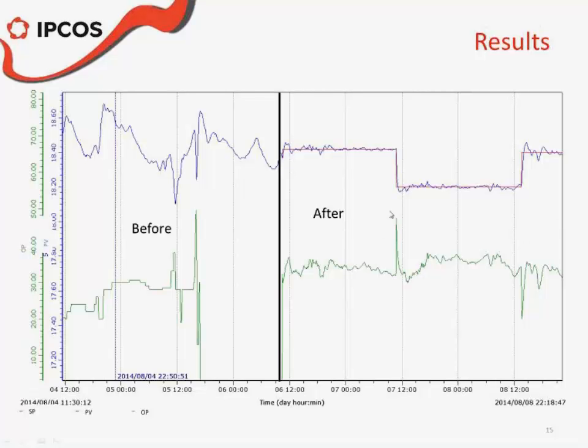Of course, it's not only the design of the new strategy, it's also the tuning of it, and that we did using our PID tuning software, Aptitune, and it allowed us to make proper tuning for this loop. This loop, as maybe all of you know, behaves just like an integrator. That's something you can specify in our software, and it will give you the proper PI parameters for you to tune it and have it control in a very stable and robust way.